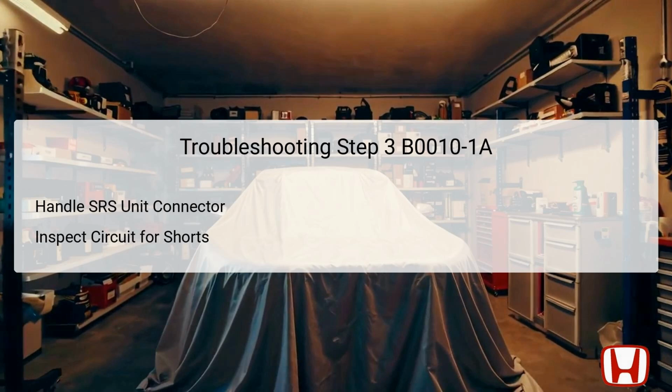In this step, the technician must disconnect the SRS unit connector A, which typically consists of 43 pins. After ensuring that the SRS unit connector is safely disconnected, it is essential to check the front passenger's airbag inflator connector as well. This necessitates a careful examination of the SRS unit connector terminals, particularly focusing on pins number 6 and number 7. These pins should be connected to the SRS short canceller for the upcoming tests.